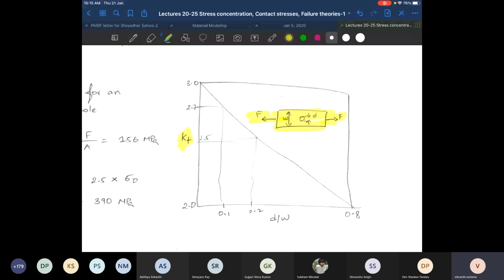Now, in this particular problem, what is the nature of the stress? Is it a normal stress that we are looking at, or is it a shear stress? As I am pulling on this specimen in the F direction, let us say my axes are x1 and x2. What kind of stress am I generating in the material? Normal stress, and that too sigma 1 1.